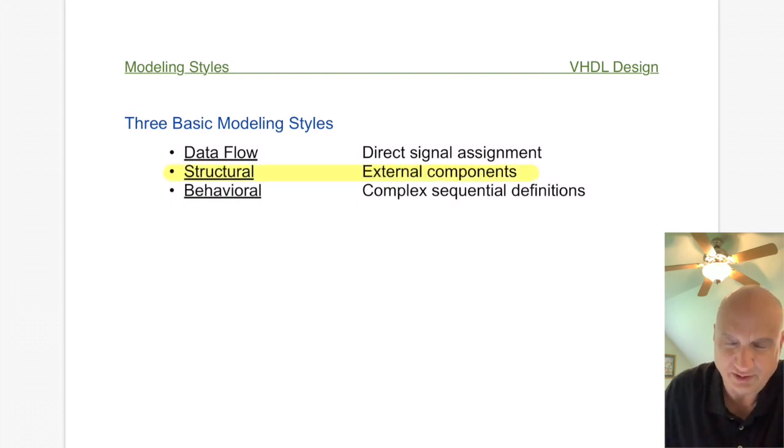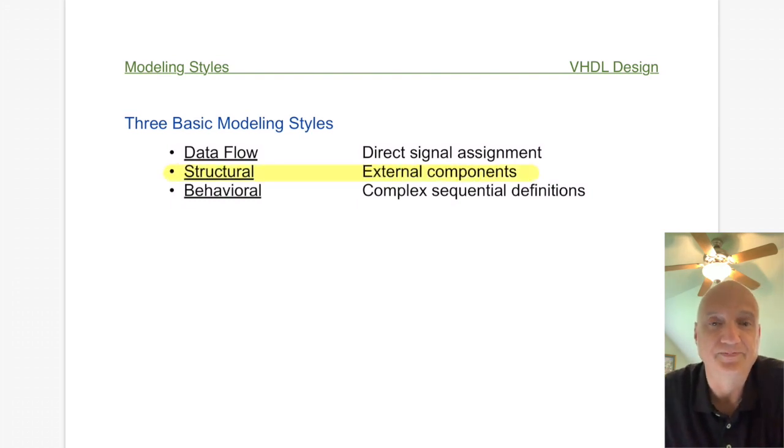Structural is the other methodology for specifying a style for a design, and that is a style that allows you to basically define a component and then plop that component into another design. So you're creating a component that can be reused over and over and over again. Structural is very powerful, and it's part of the reason VHDL is such a popular design language, because it gives you the chance to build something from scratch, test it, make sure it works perfectly well, and then reuse it over and over in your design.